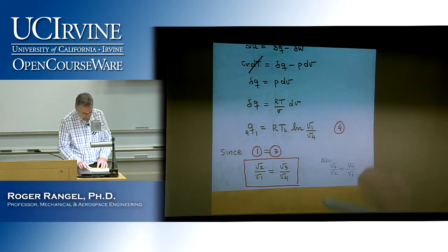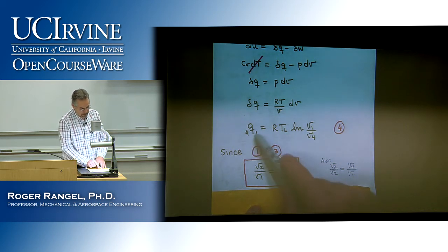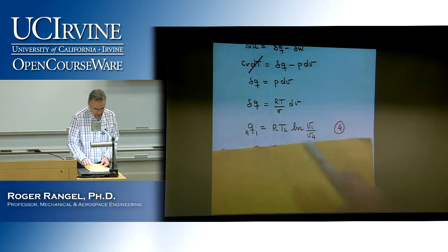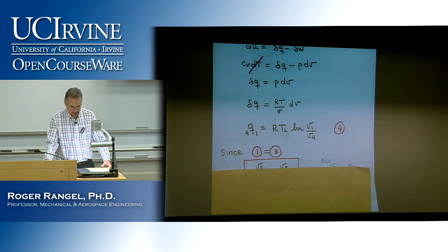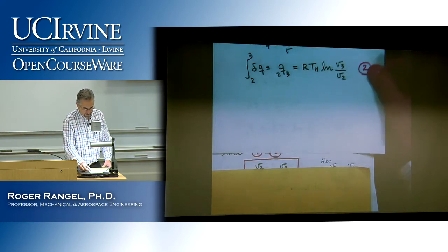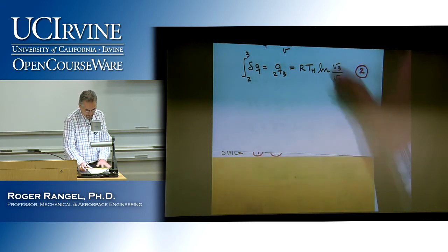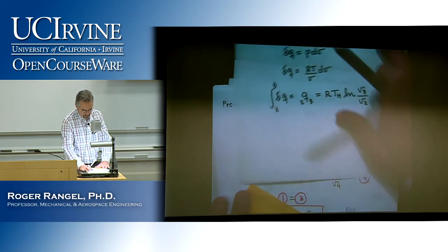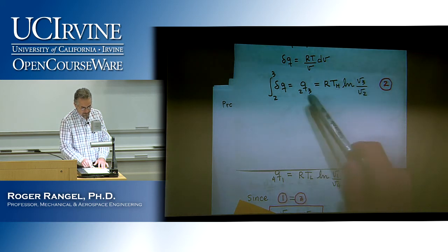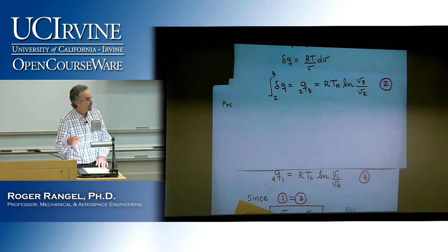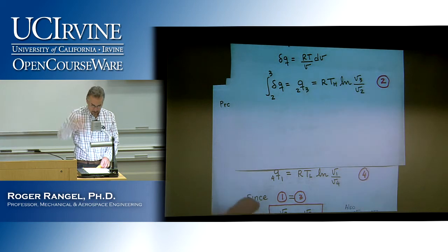But now if you think about this relationship between the volumes and you compare the 2 heat transfers, so we got Q41 is that, and look at what we got for Q23. You have it in there. So if you compare now this Q sub 23 to this Q sub 41, realize that one is the Q sub H and the other one is the Q sub L, because these heat transfers are the ones that are coming in and coming out.